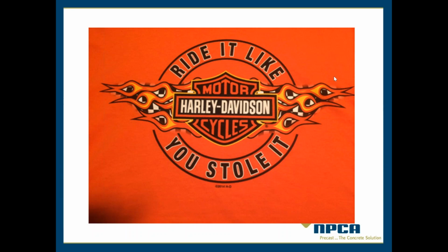I would add, for hardened concrete issues down the road, it's always nice to know what form it was poured into and where that form is in the plant. Like if you have a plant layout where you have your form and your form numbers, sometimes, there was an issue we were working through on early age cracking that related to the placement of the form in relation to the placement of a heater, or maybe by the garage door, so suddenly you find a trend in something like that. And it just takes a minute to do a layout and have that documented, so you can always go back and try to figure it out that way.